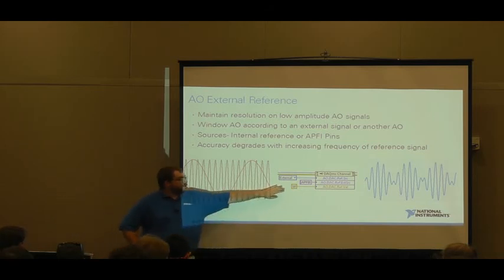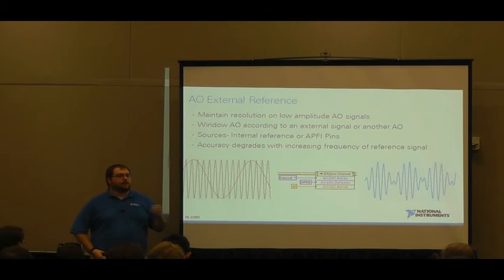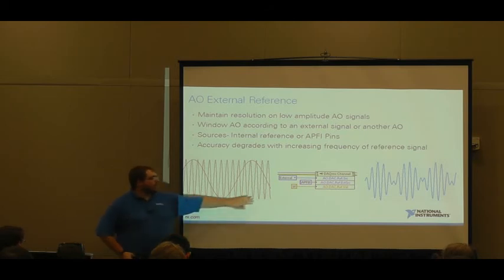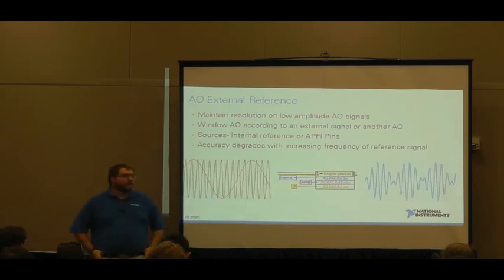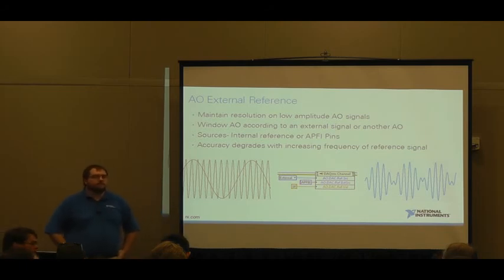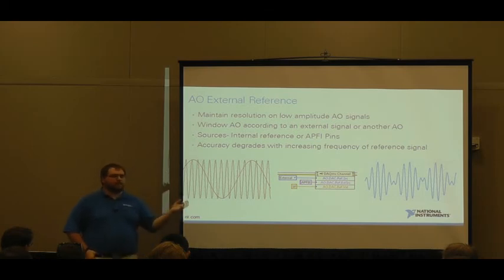So this is used for scaling the data that you write to the task to the correct thing for the DAC. You're right, it doesn't strictly have to match exactly what it is, but your results will be scaled by that amount. So if I say I'm putting in 1 volt, I'm actually putting in 10, then if I say I'm going to call out 1 volt, I get 10 volts out. Because you have to think of it as, we use this to calculate from the value you specified to what digital value to program the DAC to. So if you lie to us on one side, you'll get the result of that back out.